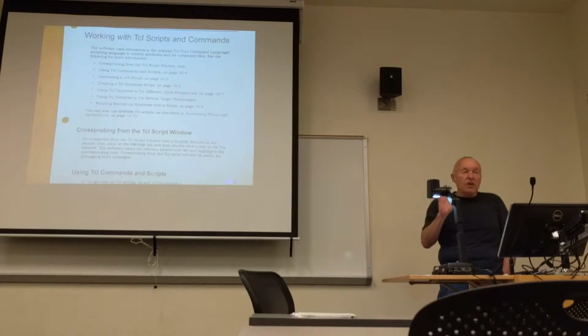But examples of things that you would put in the Tcl file is, you recall that when you use that GUI to do your synthesis, one of the steps you had to do was go to a drop-down menu and select your FPGA. Well, there will be a Tcl command in there that says, this is the FPGA I want to use in this particular synthesis. Your pin assignments can be put into the Tcl script file.